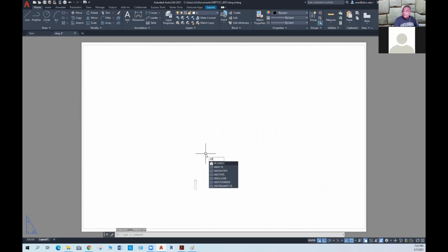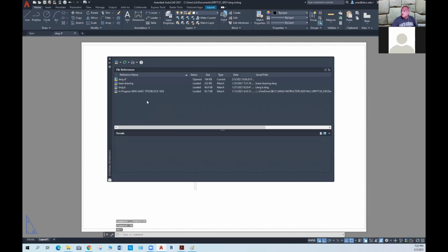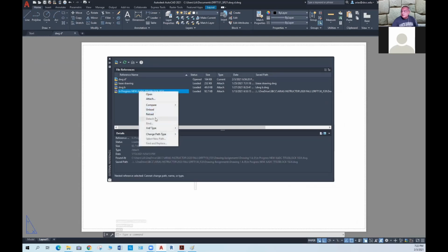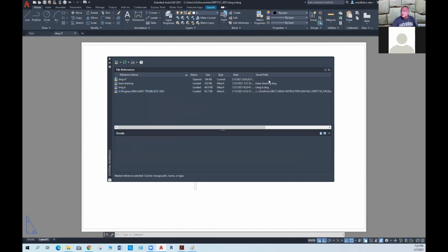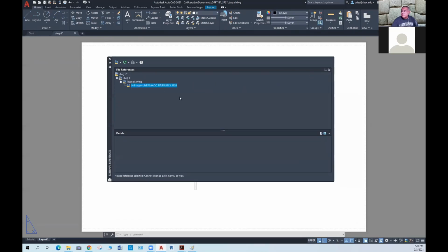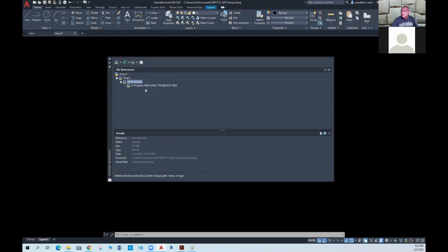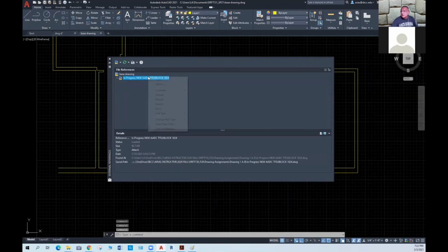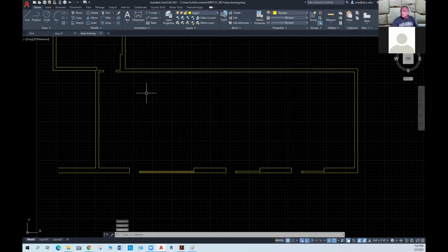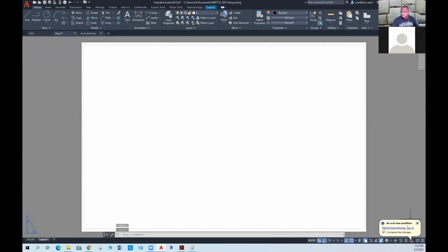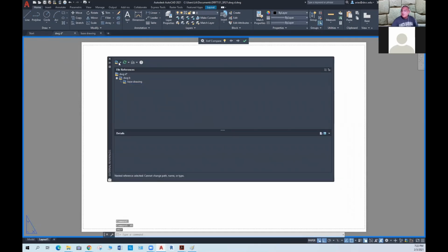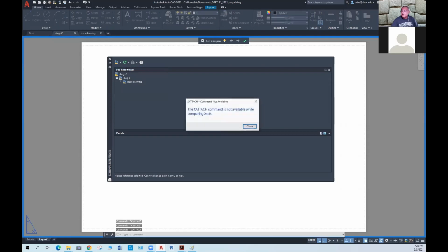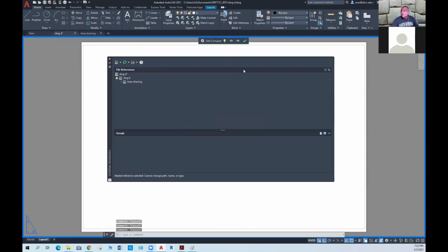And so XR, and I'm going to go to, let me detach this. Oh, it's not even there. So see why is that there? Oh, base drawing is habit. So let's open the base drawing. And here I'm going to detach that because I don't want a title block here. The title block should be in the D drawing. Okay, so XR. And so now I'm going to select attach DWG. Oh, it's comparing XREF, so that's fine.